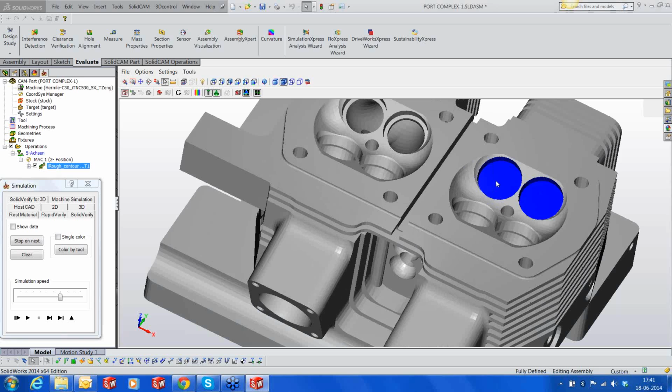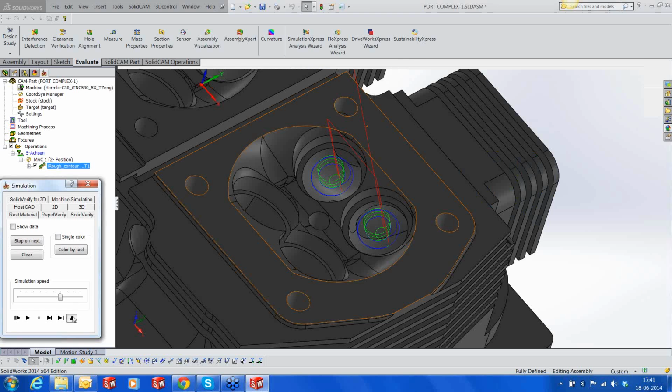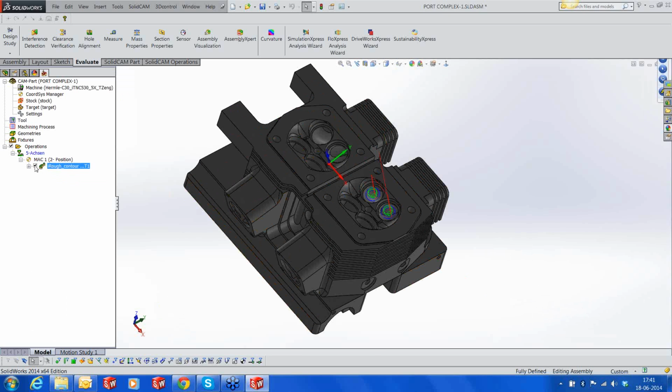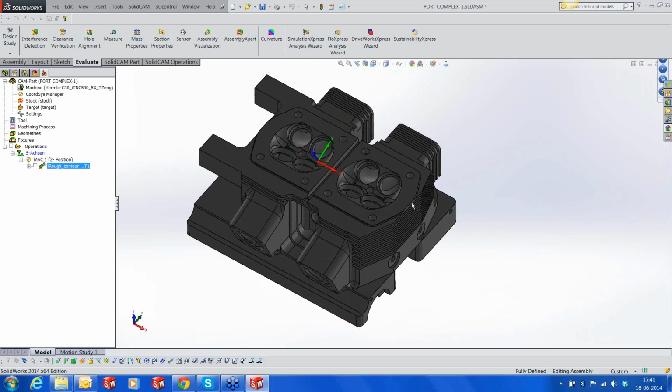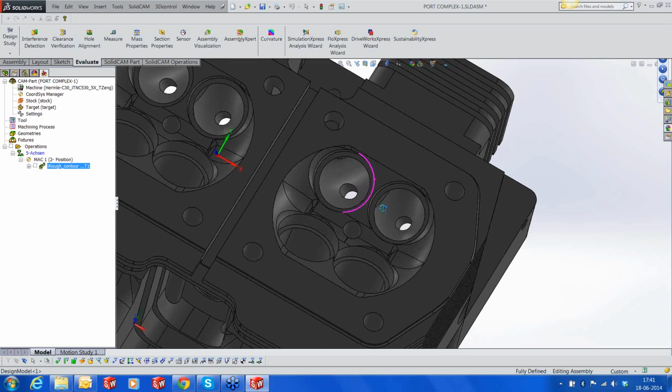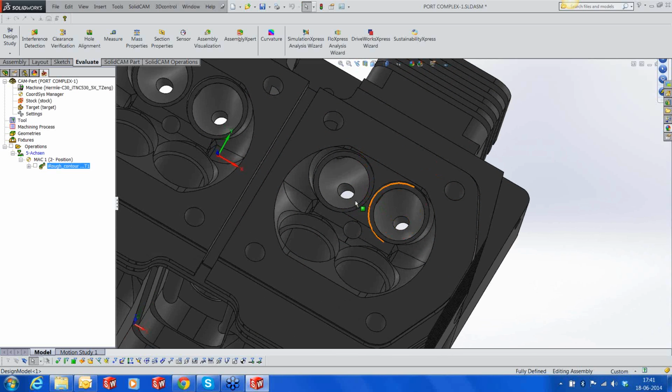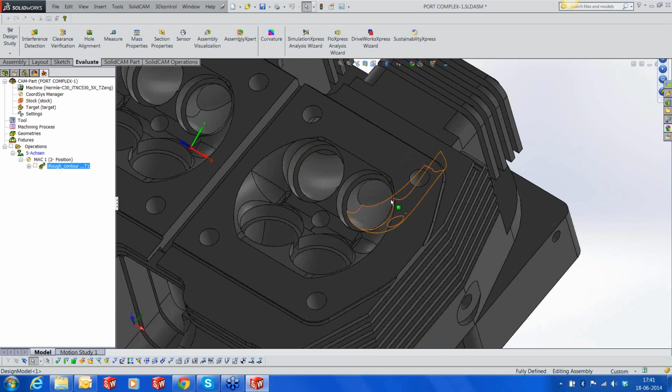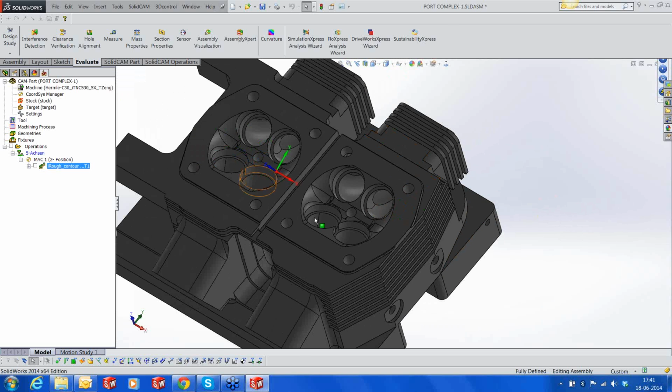And from here, now we can start cutting our port geometry. All right. Let's switch off. Now to cut this port, I'll make slight modifications to the geometry. I'll tell you why. The port machining engine of SolidCAM doesn't like these holes, so I have to close these holes. And I have also to ensure that I give the system single tubes as much as possible. So we're going to do some small geometric modification, but we're not going to change any geometry as such.